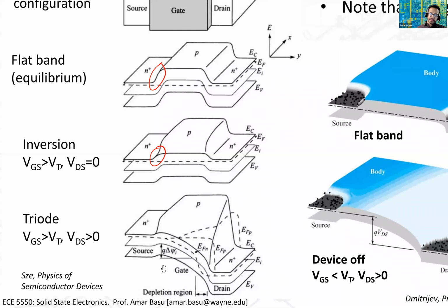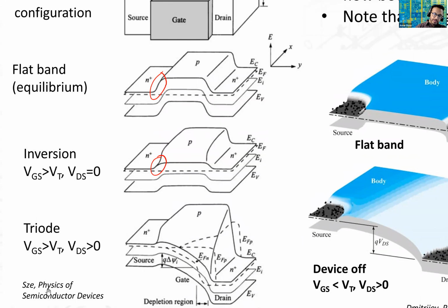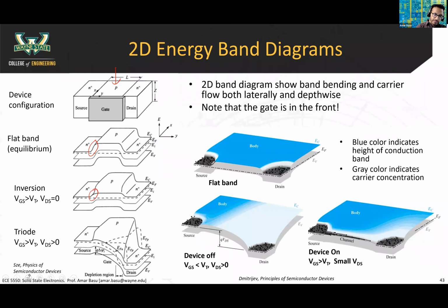Okay. I'm just going to circle again the energy barrier. So the electrons can, when you put a gate voltage, you reduce the barrier, and then you also put a voltage on the drain. Now the electrons can overcome this barrier, and once they do, they just go down this way and follow that into the drain. And when electrons flow from source to drain, your current is going from drain to source. So that is the visualization of how current flows.